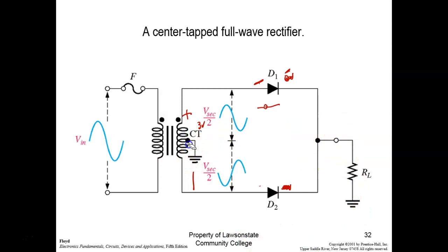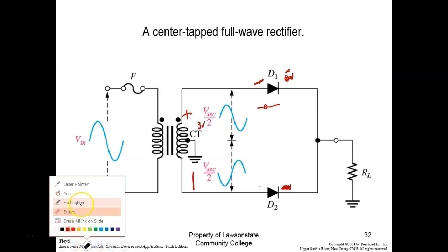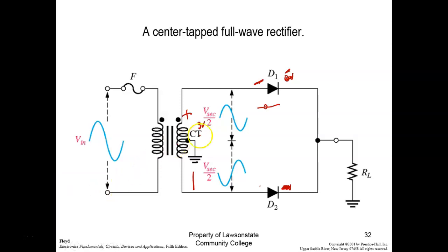So what I know is since this is hooked to common, that the current flow is always going to come out the common, right? Because that's, in this situation, it's the negative, right? Y'all understand what I'm saying so far? So I know the current is going to flow out of this, since this would always be negative in respect to what it's measuring. Then current's always going to flow out this one, but it's going to do what? It's going to flow up there. Since this is considered the negative, the bottom of that resistor will always be negative, and the top of it will always be what? Positive.